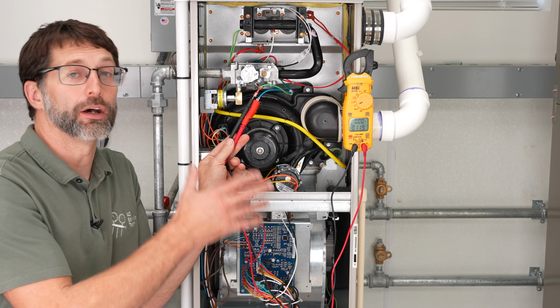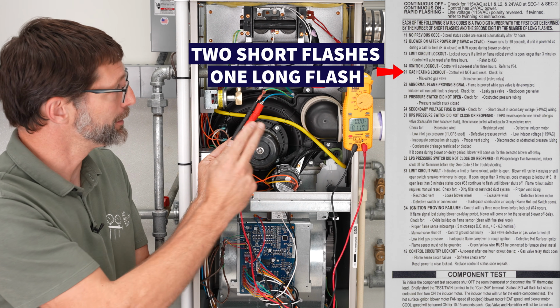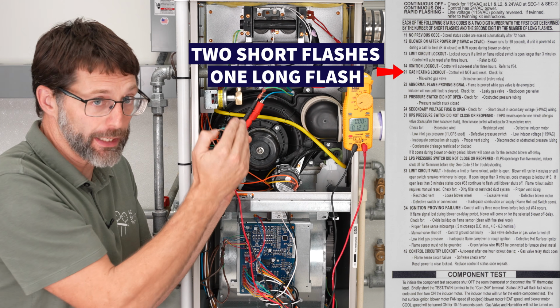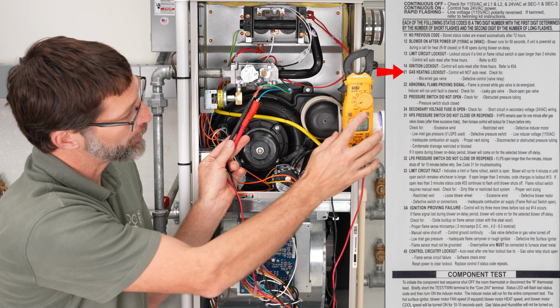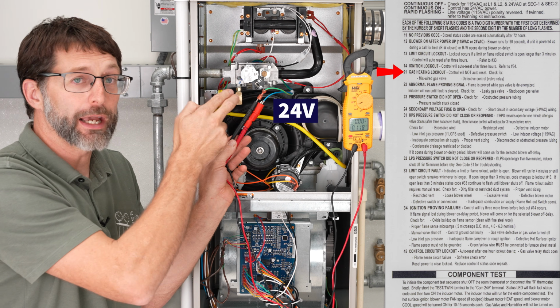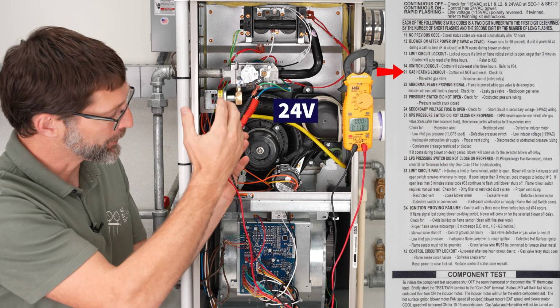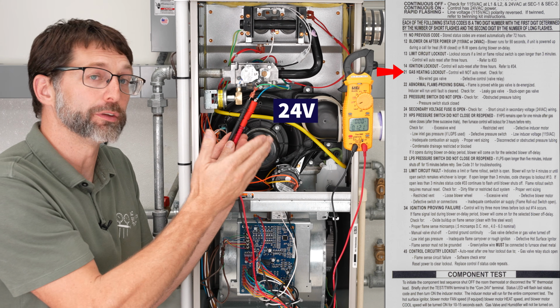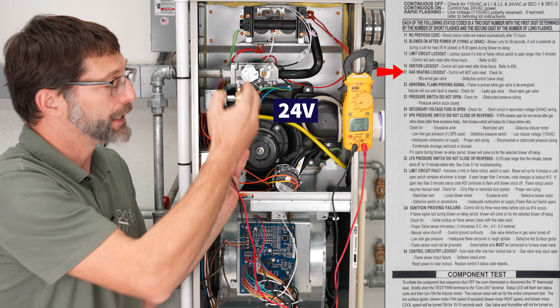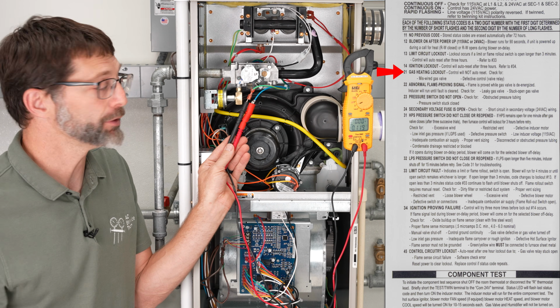On this furnace, error code 21, which is 2 short flashes, 1 long flash, means there's something wrong with the gas valve. Of course, you can measure your voltage with a multimeter to make sure that you're getting 24 volts right over here at the gas valve, but maybe something on the inside has shorted together, and so basically the control board is throwing a number 21 signal saying that the gas valve may need to be replaced. But we're not going to be able to show that error code on this one, so I just wanted to describe it.